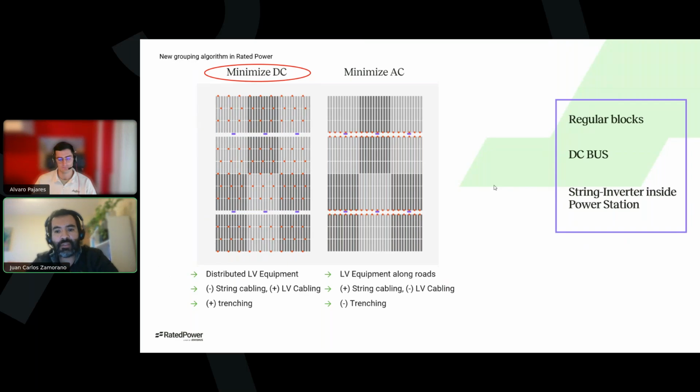These are MVLV strategies because by choosing any of these, we're taking a big decision about the main equipment configuration and how it should be placed in the layout. Features like border adaptation, rotation, and so on are more optimization features and come right after this MVLV strategy decision. That's why the MVLV strategies are foundational stones for PV layout.